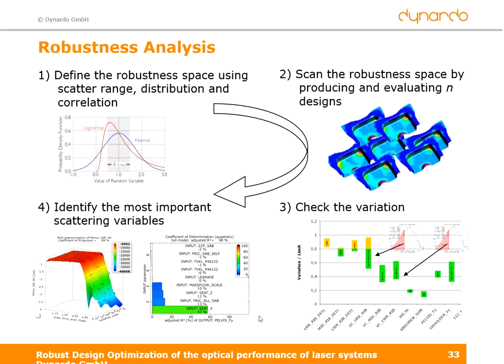That means that you can really find out which are the critical input variations that lead to the fact that you exceed your limit, and which inputs are safe, where you can even widen these input variations in order to save money. And yeah, this is actually the concept of the robustness analysis.